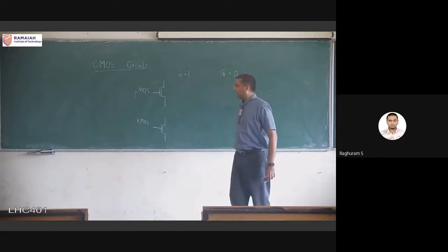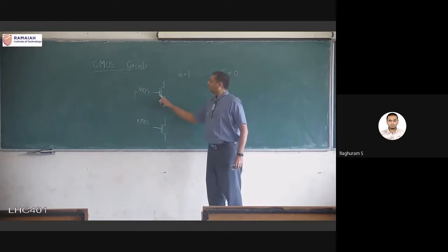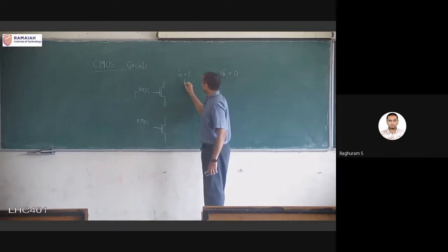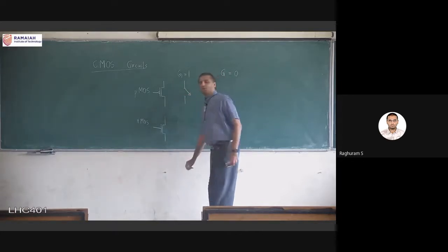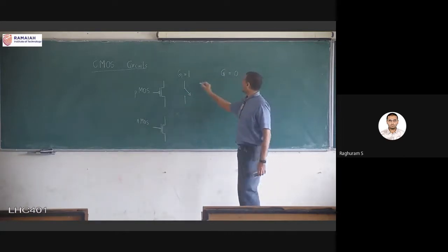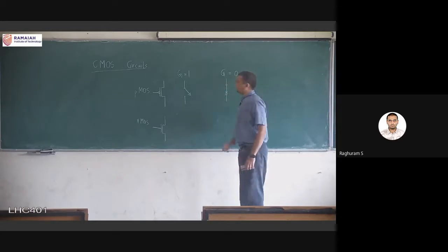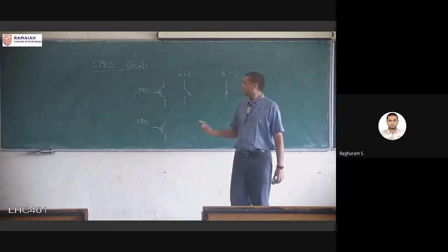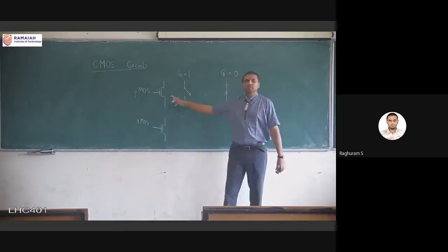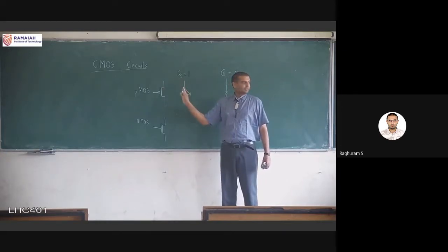Okay, and we will just look at the equivalent circuit. PMOS transistor, this is the circuit symbol. When gate equal to 1, this is represented by an open circuit, and when gate equal to 0, the same PMOS transistor acts as a closed circuit. So for the basic functionality level, this is all we want. The 3-terminal device becomes a 2-terminal device because the gate is out of the picture. After the gate has had its effect, it will just be on or off.